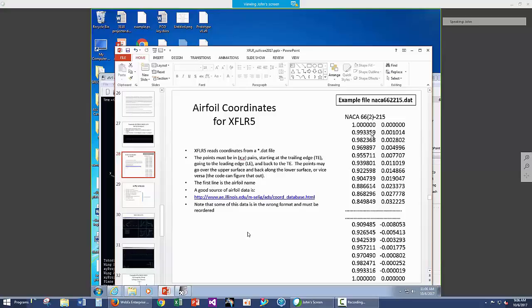Your airplanes, for the most part, are going to be cruising at Reynolds number of order 200,000, which is very low. But there's quite a few airfoils that perform well there, and perform well from lift coefficients of say minus 0.2 up to 1.2 or so. There's a couple of Seligs that have a tremendous amount of camber in them. That also will work up to a CL of 1.5. The problem is they're going to start to stall on the lower surface at maybe a CL of 0.5, which may not work for your airplane.